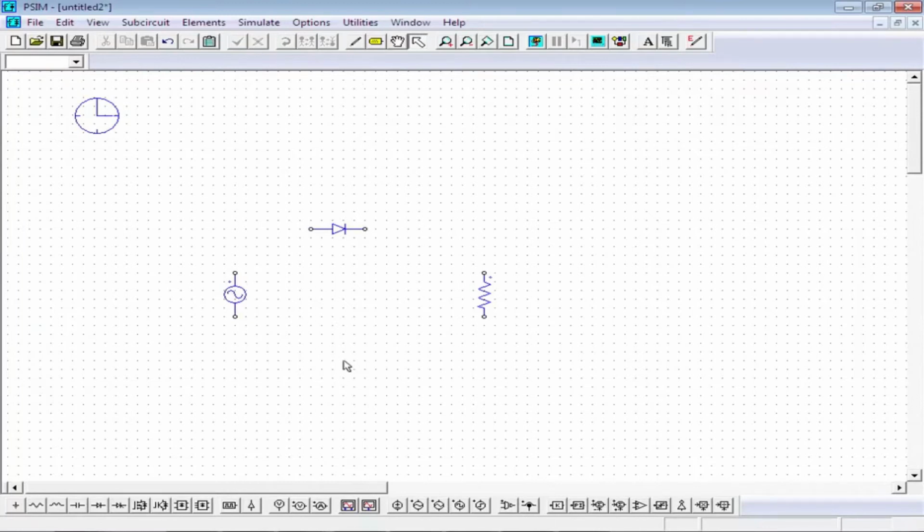Now to connect these four things with each other, we need to have a connection, and that is made, you can see on the upper side box, there is a wire written here. So if you just click here on this hollow button like this, and drag it, it will eventually connect the circuit. The correct connection always has a red line with it. So if you are having some green line, it means there is something which is floating. And then you will connect this to the load, and just connect a ground here, and you are finished.